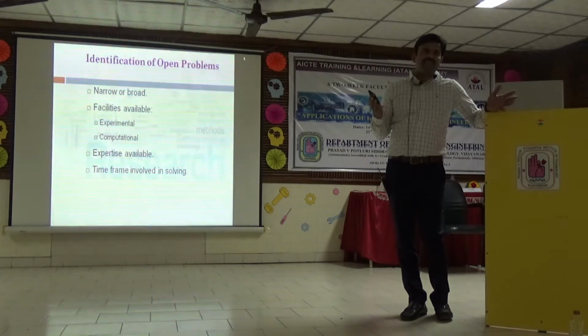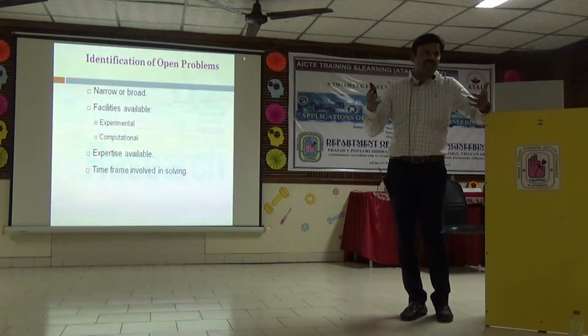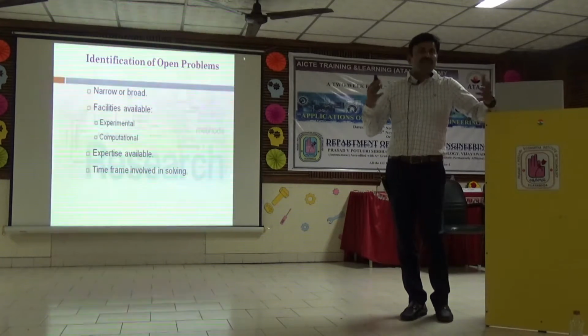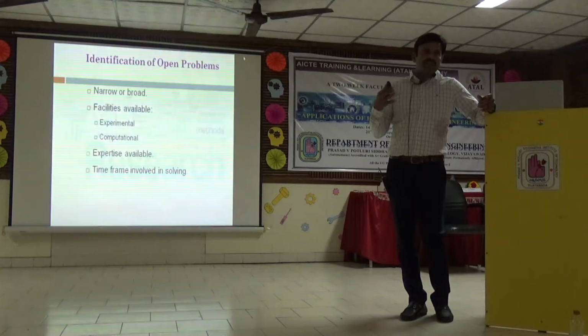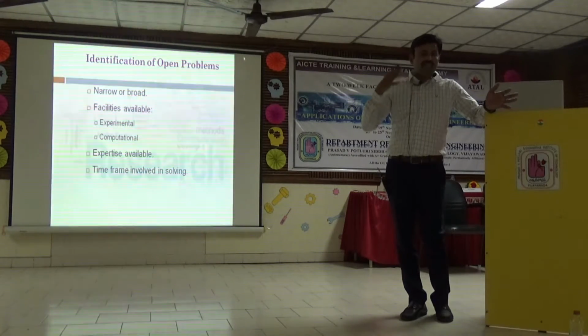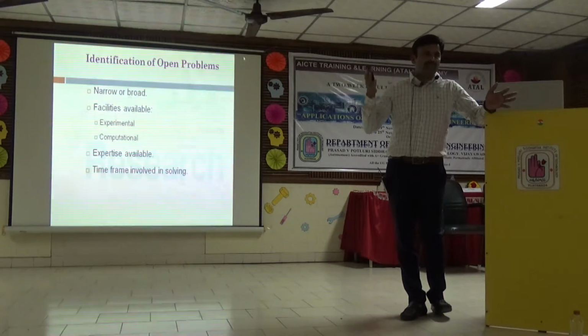Basically, the frequency of the table should not match the frequency of the building I am constructing. So we built and fabricated the table such that its frequency is 10 times more than that of the building. So we do vibration analysis.